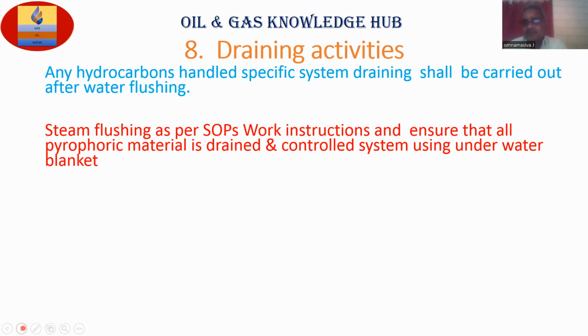So before draining, you should ensure that a water blanket is in place. Why is it required? This pyrophoric material, when exposed to atmospheric conditions, within 5 minutes a big fire will take place. That much danger is in this pyrophoric material.